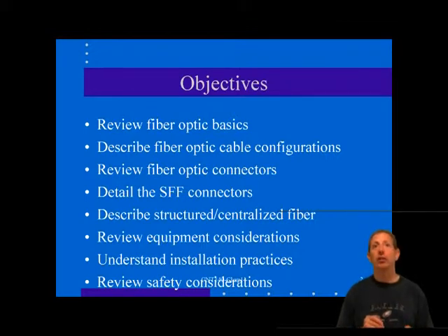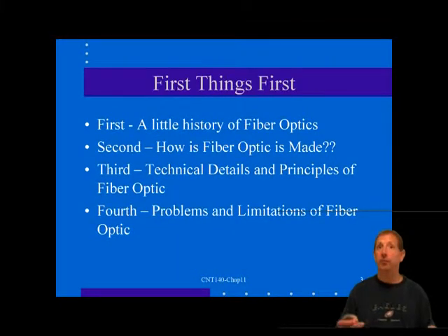Optical fiber was initially used for intercity telecommunication links to replace antiquated and overloaded microwave links at a lower cost than satellite. In this application, T-carrier links and later SONET links provided extensions of the telecommunication services over long distances. The intercity fiber featured advantages of long range, wide bandwidth, interference immunity, and relatively low installation costs compared to the bandwidth provided.